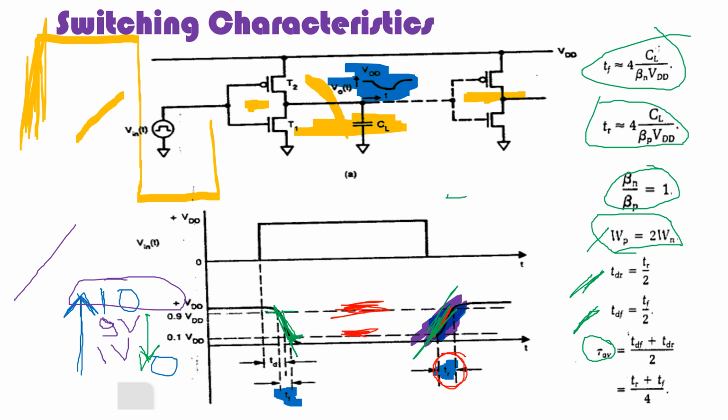And we have something called propagation delay also. That delay is nothing but, mark the input. So you can see the purple color which I am shading here. So this is the input, where the input is shifting from 0 to 1. And here is my output falling. So mark the 50% of the value here, and here also mark the 50% of the value, and see the difference. Say it is 1 second here and 2 seconds here. Then 2 minus 1 second will be my propagation delay.